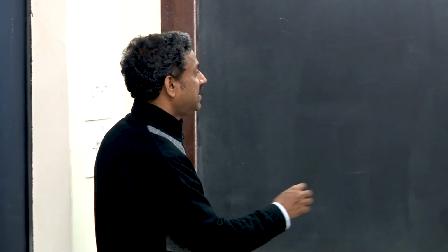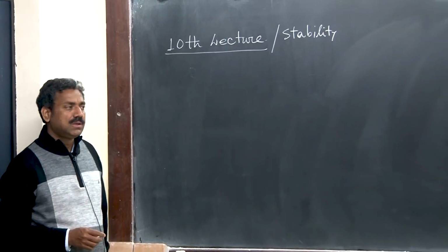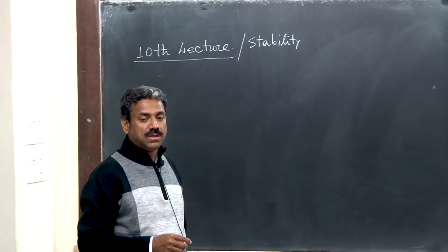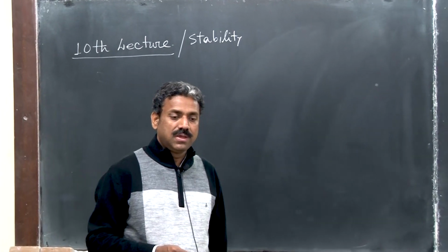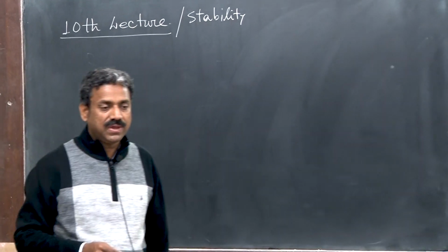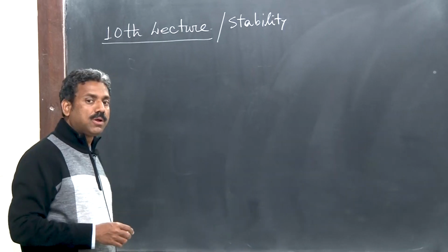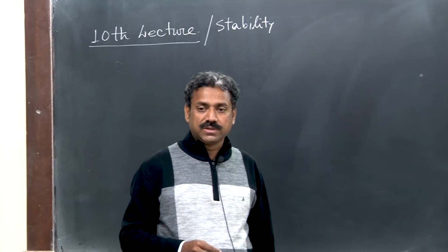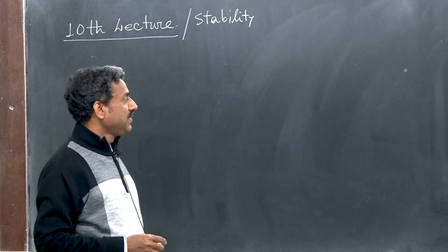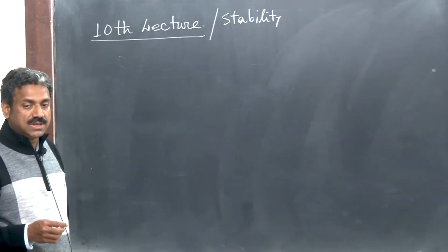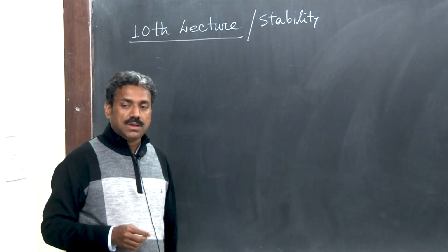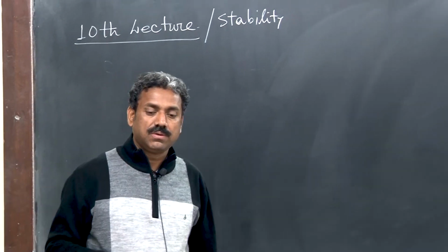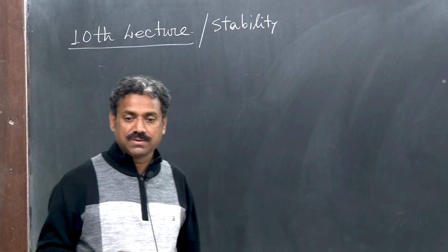So, what we are discussing, let us briefly recapitulate. We started with the torsional flexural buckling of columns, and we have emphasized the role of warping of cross section in open sections, especially thin-walled open sections, the design of which is many times governed by this torsional flexural buckling.